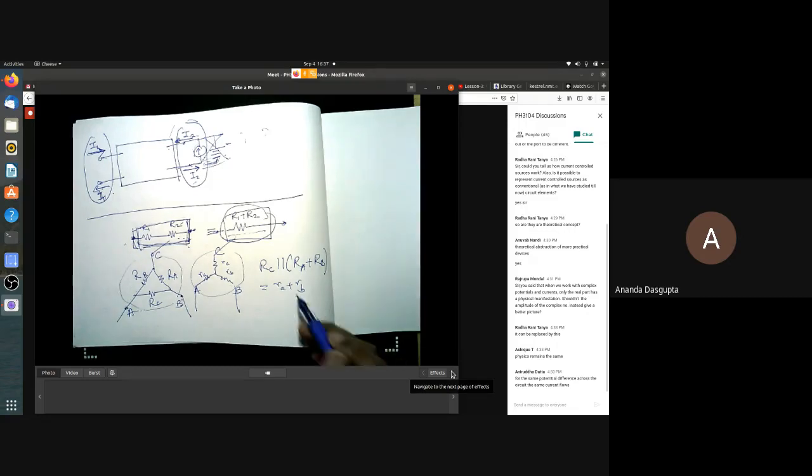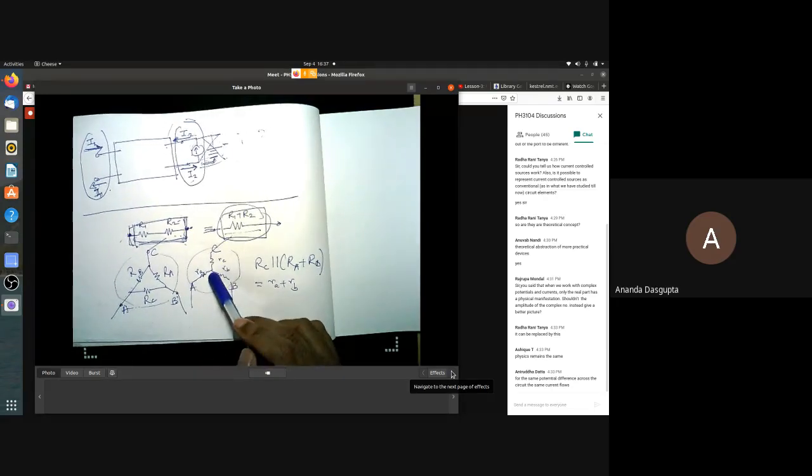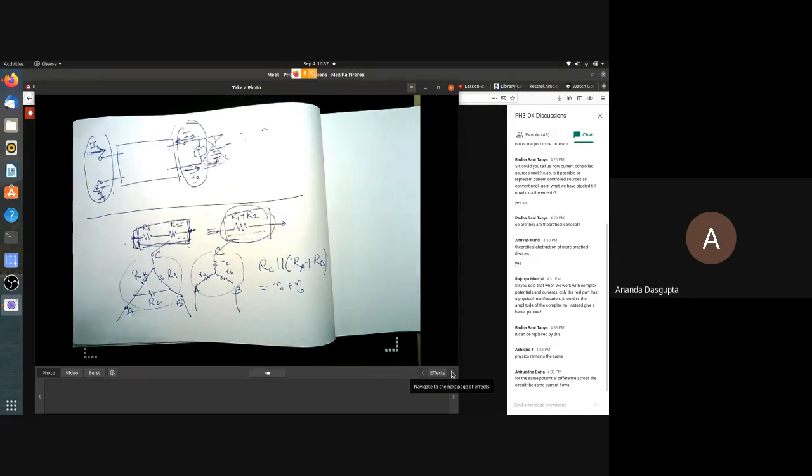Now the proof, that is the calculation that is usually done to derive the values of the star delta transformation, assumes one very critical thing. It assumes that there exists for every delta really a star, or for every star a delta. Once you make that assumption, that no matter what you connect to ABC, the star and the delta will behave the same way, or really they will look the same from the outside world.